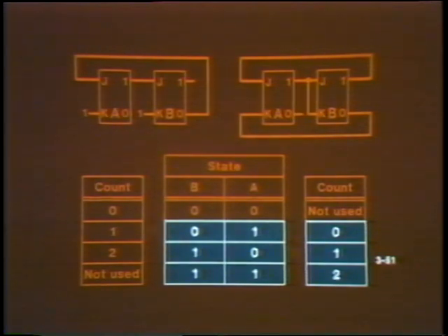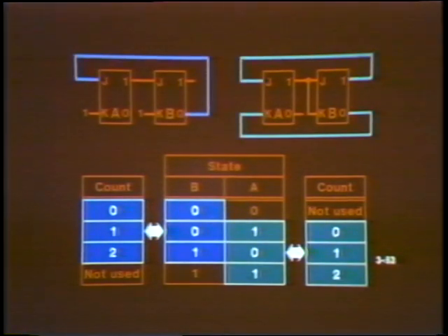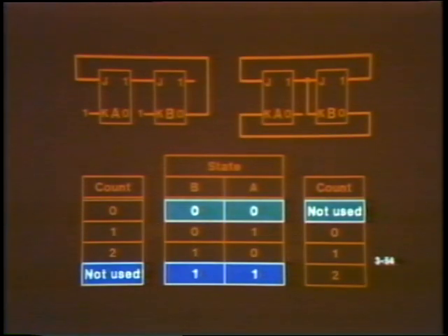There are usually many ways to design non-binary counters. The alternatives depend on the designer's choice of which counts to assign to which states, and the resulting feedback, which causes the circuit to cycle through the specified sequence of states. Non-binary counters are usually a bit more intricate than binary counters because there will be unused states in a non-binary counter.